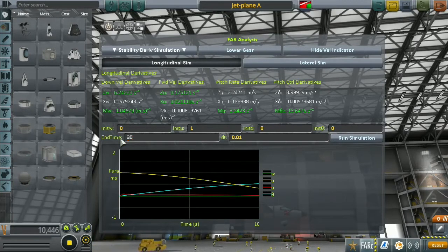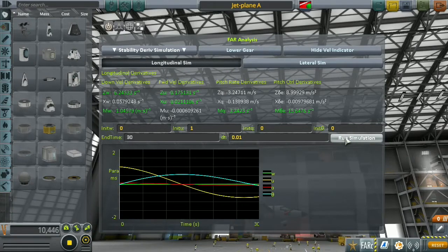That's not all actually, because what happens in the course of 30 seconds? In the course of 30 seconds, the aircraft will at some point be back at its normal speed, but at that point the aircraft will be in a slight climb, which means we will continue to lose speed. Then at some point the aircraft starts to build up speed again.